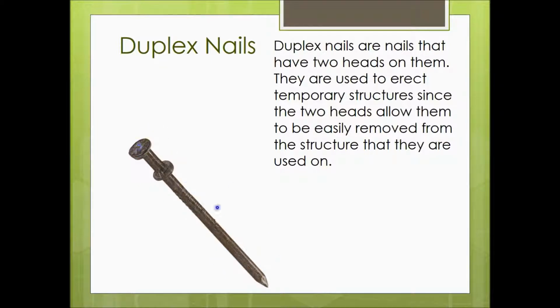In a few days or weeks, when I get ready to wreck whatever I've constructed, when I get ready to tear it down, I've got a nice head sticking out here. I can just hook my hammer on and pop it right out. So these are made for temporary construction. All right.